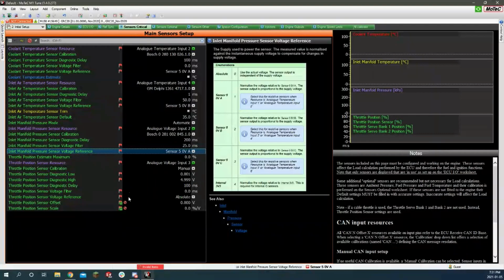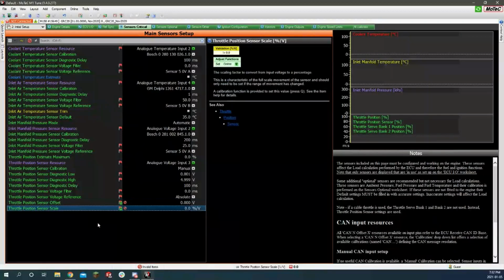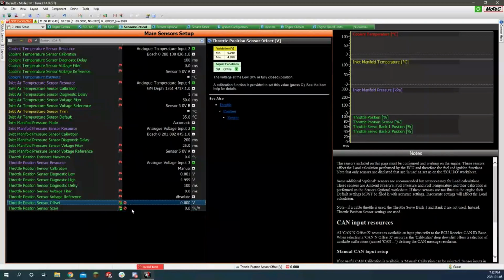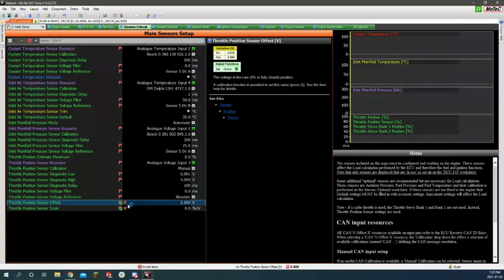This is something interesting where it says Q. So when you're calibrating your throttle position sensor, it has to know mechanically, depending on your mechanical setup, it'll have a starting point of a certain voltage, and when you floor it, it'll have a different voltage. So there's a little, like I think a wizard that takes you through it basically, to calibrate these two. And Q in the Motec software is like the key that says calibrate now, calibrate according to current conditions. So you can use that for lots of different things, and I'll get into that briefly near the end.